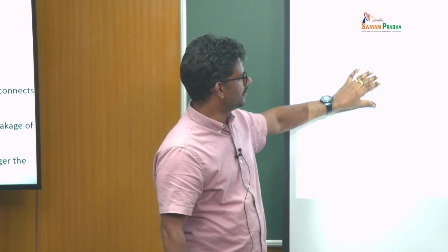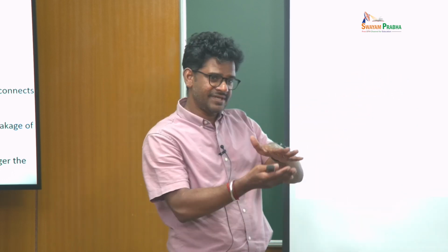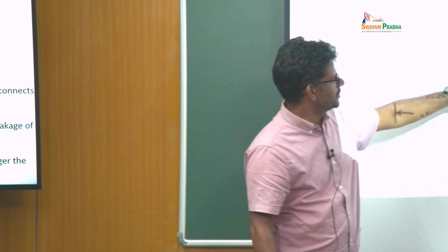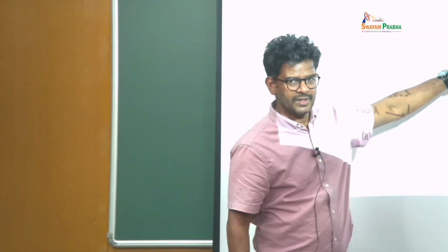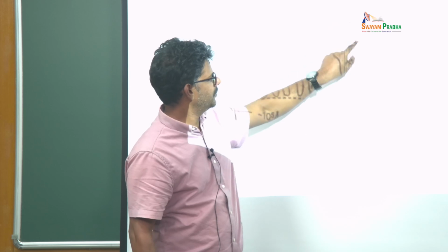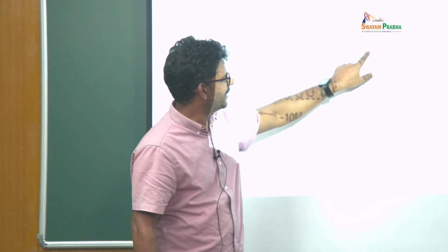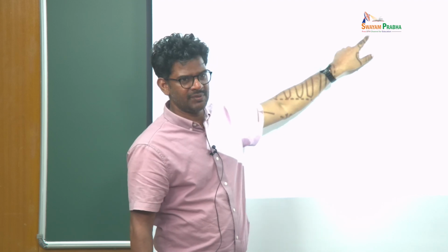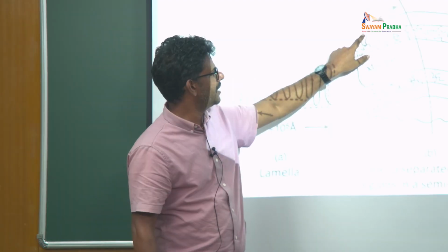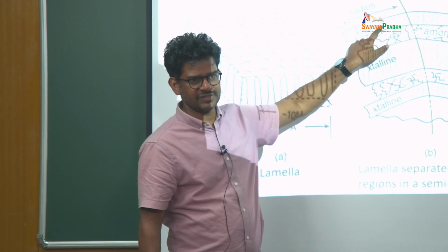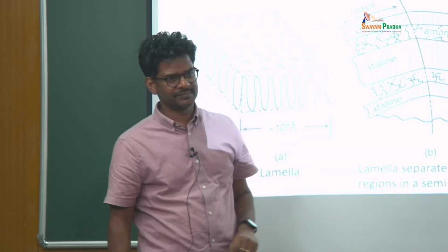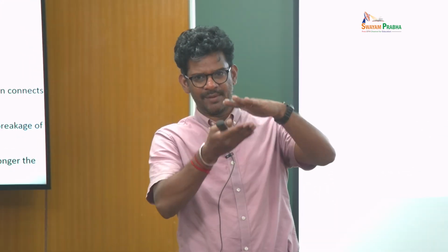Now this one can be stacked further. You see this is one lamellae, this is another lamellae, and between them you have some amorphous polymer. Polymer basically packs here, and extra polymer can go and become a little bit irregular, and then it can take part in this kind of crystalline arrangement in the subsequent lamellae. So typically a crystalline polymer is basically a stack of lamellae. Between those lamellae you will have this amorphous